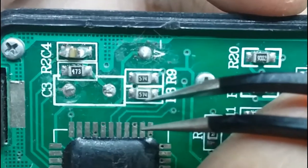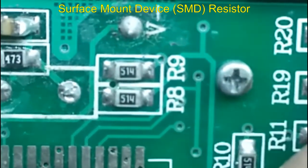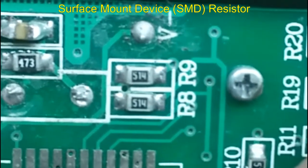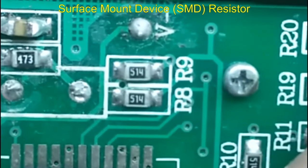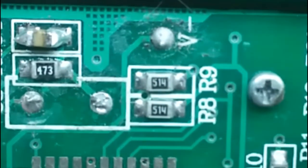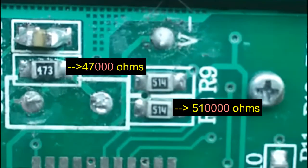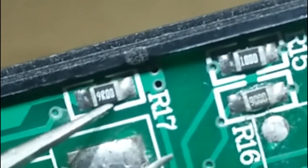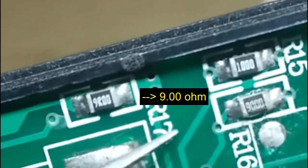But if you see an SMD resistor like this, it's the same idea as the color code, but it's much easier. No need to memorize the code because it's directly printed in digits. The last digit tells us the number of zeros to be added. If you see the letter R, just imagine that it is a point, so this will be a 9.0 ohm